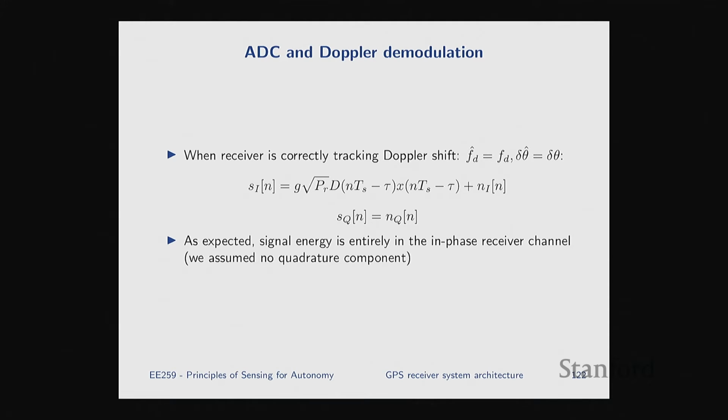Okay, so now we are on to something, right? Because if you look at here, we have gotten rid of all the carrier modulation and the Doppler shift, right? And we have come down to what we care for. We want to get to a point where we just have the delayed X, and then we can correlate it with our local replica and find the peak. And we are very, very close to that. In fact, we are exactly there.